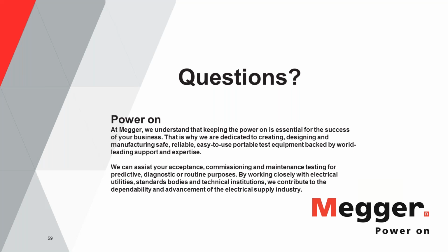All right. Next question, is reducing instantaneous settings on a circuit breaker still a valid test? For example, a 12-times setting of 52,000 amps instantaneous is tough to get in field situations. Is reducing the setting to 4 times valid?